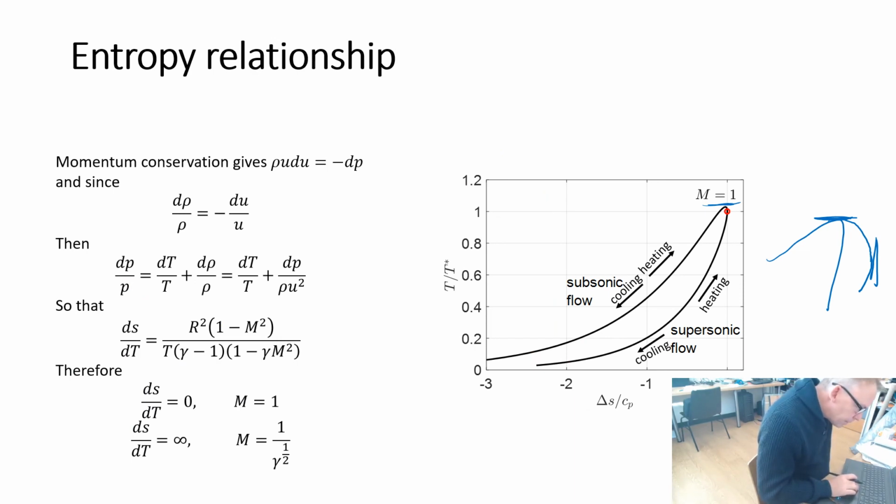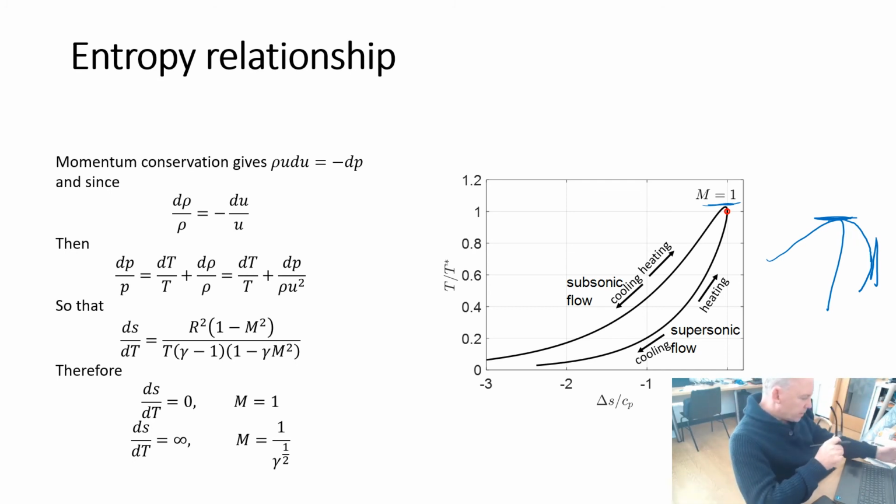The main point about looking at entropy is that the maximum entropy occurs when the Mach number is 1. And this is actually used when we're looking at detonation fronts. A number of people have tried to explain detonation fronts in a number of different ways. So I prefer the Rayleigh Flow description, much more intuitive, this idea that you're pushing everything towards Mach number 1,